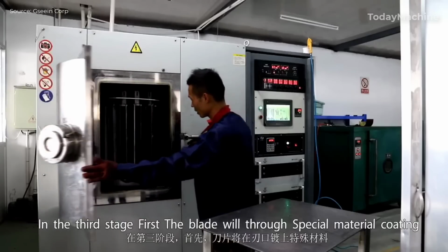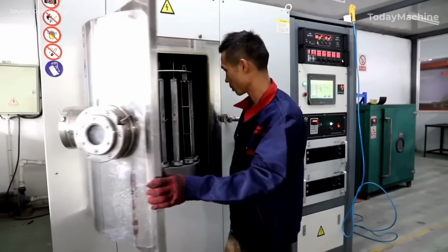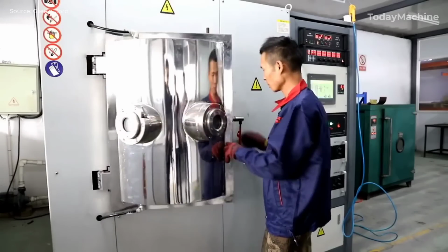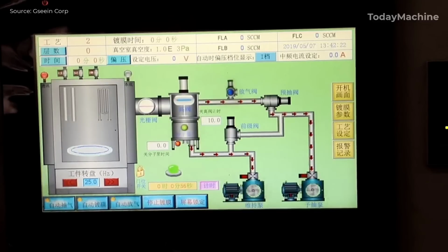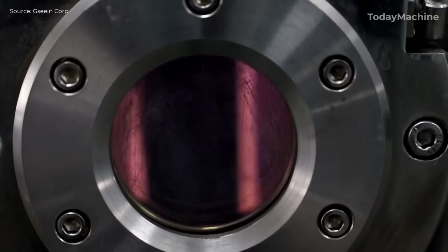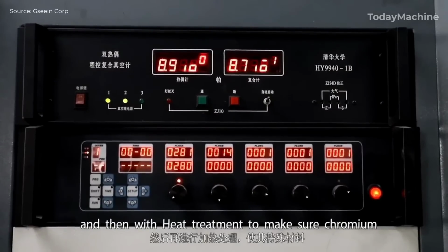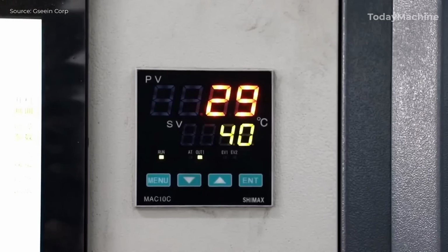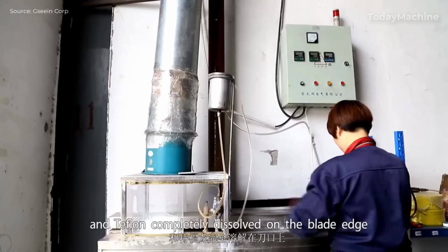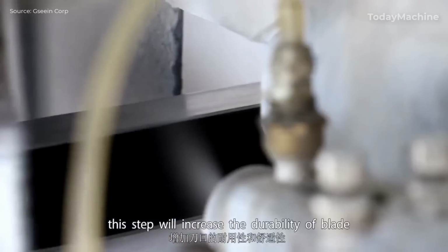In the third stage, the blades undergo special material coating. The first coating layer is typically a protective material, followed by a Teflon coating on the edge. The blades then undergo heat treatment to ensure that the chromium and Teflon coatings are properly fused to the blade edge, enhancing its durability.